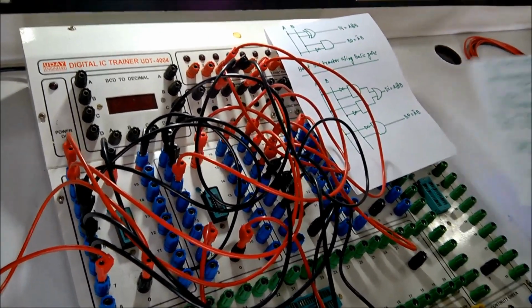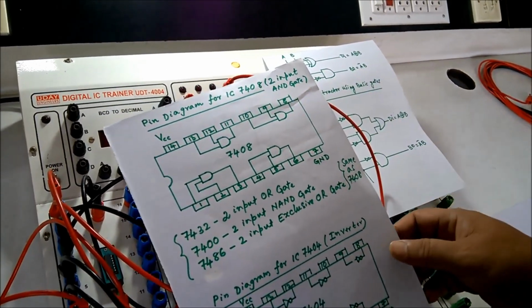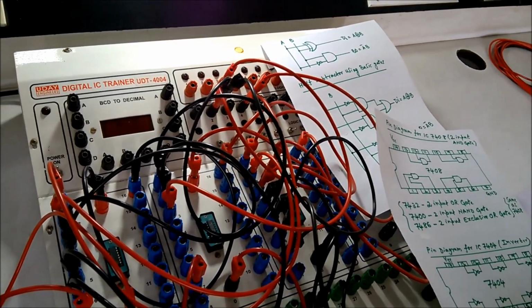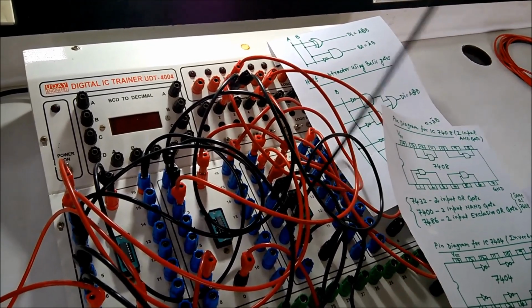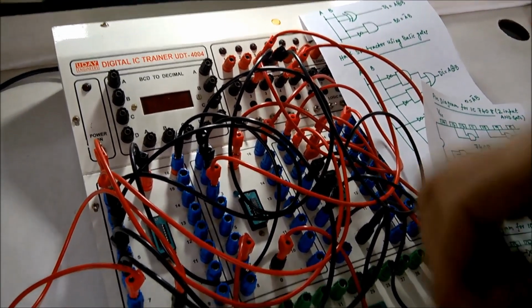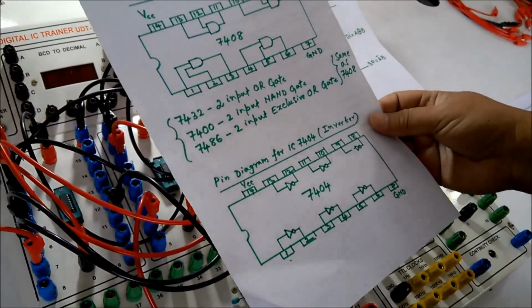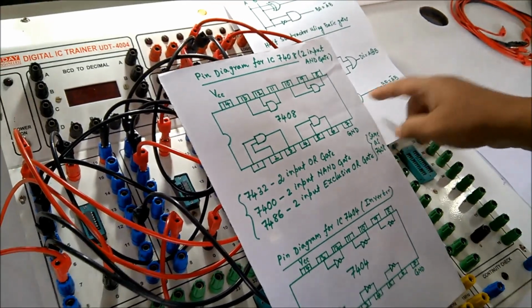I will be using another AND gate. This is the AND gate. 9 and 10 is the input. Therefore, I am putting this complement of A into the 9. And another is coming from B.